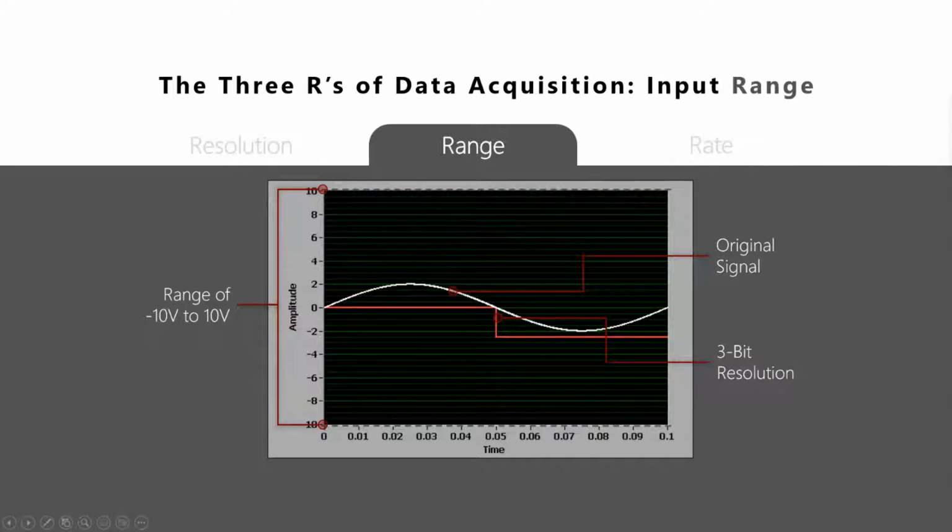If our signal is small, it would only take up part of the range of the ADC, so we would only be able to detect and represent 2 possible values. It only utilizes 20% of the range of the ADC. So we can do 2 things to address this. As discussed previously, we could amplify the signal, so instead of just using negative 2 to 2 volts, we could amplify it to a range of negative 10 to 10 volts.